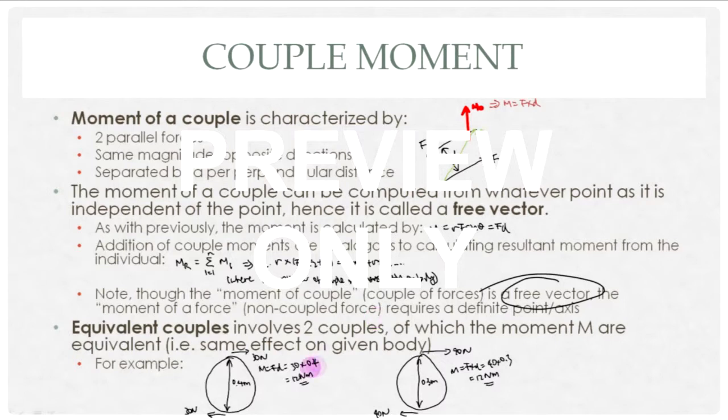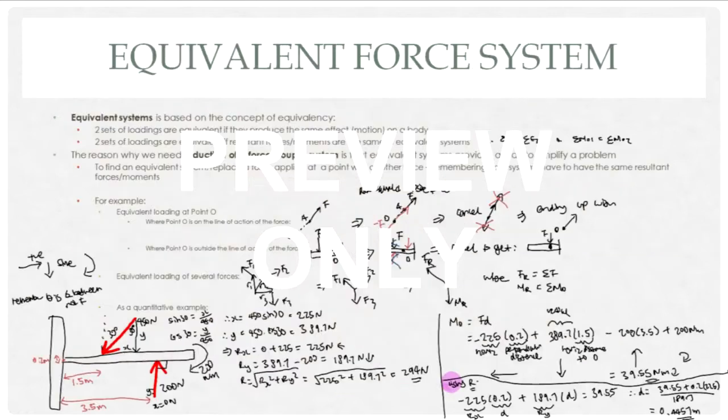So for example here, I've got a hand that's spinning it. So I'm pushing 30 newtons there, and it's multiplied by 0.4 meters. So if you multiply, it's 12 newton meters. Here on the other hand, 40 newtons and 0.3 meters, and it's 12 newton meters. So these are both exactly the same. However, it involves two different couples altogether.